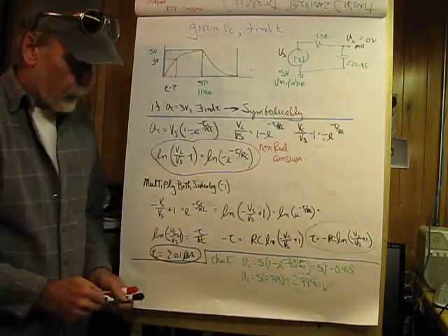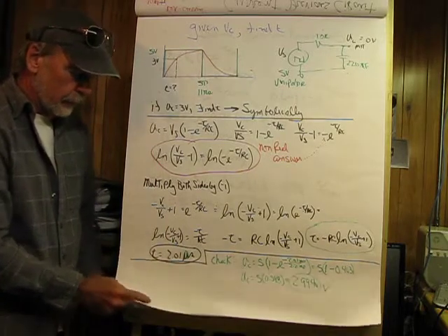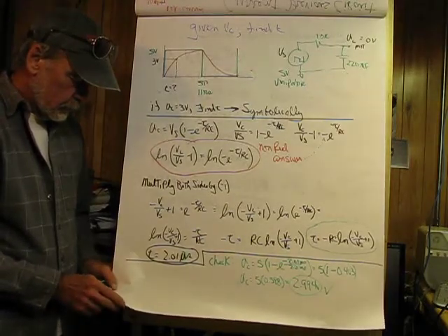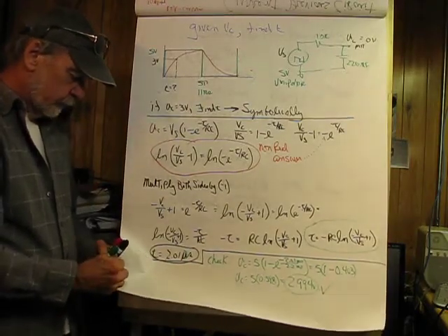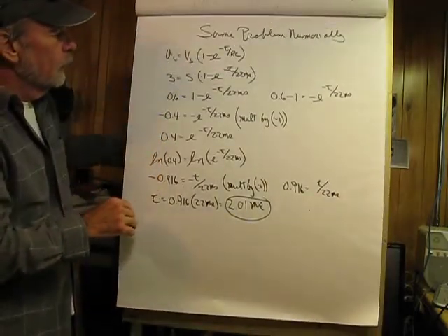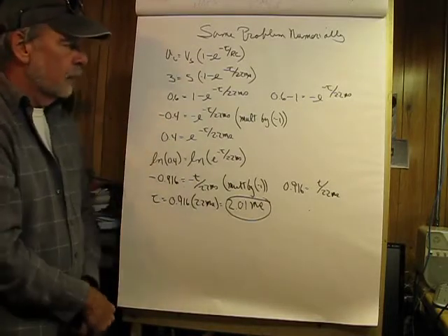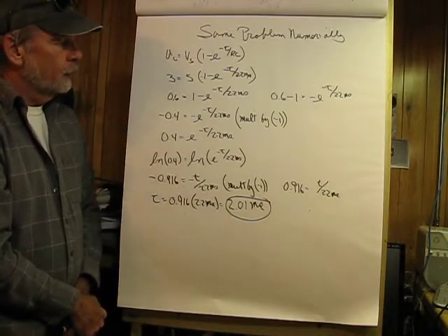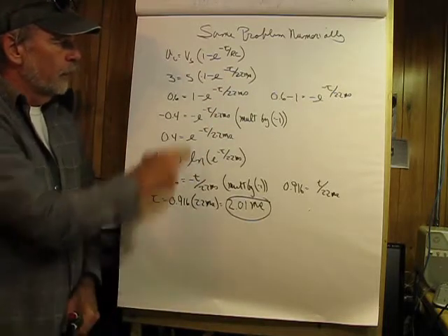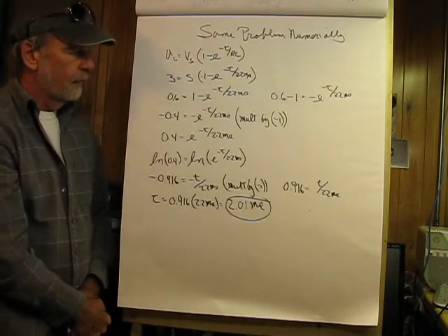Now, let's do the same thing with numbers, and this should be, I think, a little bit more comfortable because we can combine things. So here's our starting equation for the charging exponential, and we're going to start by isolating t again. So we want to get rid of our VS here, which is a multiplier or source voltage, which is 5 volts.